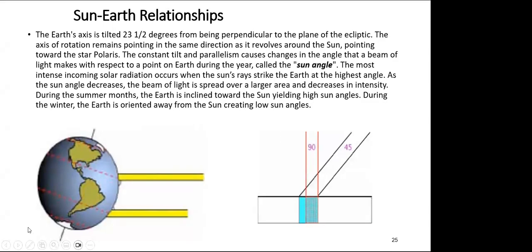Now, why is the declination angle important? You can see the radiation here. The energy content of this amount shall be the same. If it comes to this point, the surface area is much smaller compared to this surface area. For this energy, A1 and A2, A2 is higher than A1. Same energy, but if we find out how many kilowatt hours per square meter, the energy here is divided by A1, and here the energy is divided by A2. You can see this is a high amount because A1 is much less. This one is much higher than this one. This is the energy intensity.